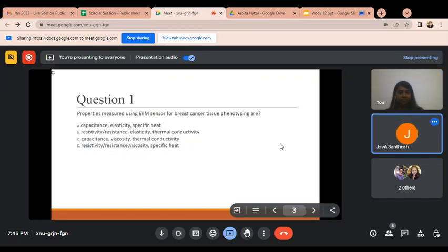Once again, ma'am. In positive photoresist the area which comes into direct contact with the UV rays, when we go for developing, dip the wafer into the developer, this portion will go. Yes, ma'am. Now I can understand, ma'am. Okay.